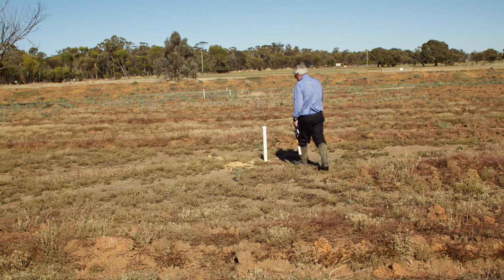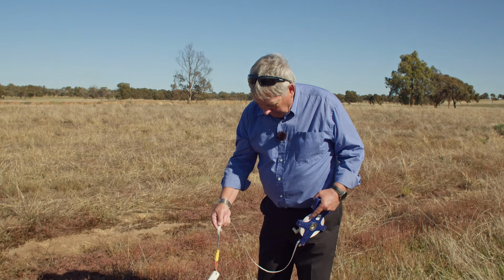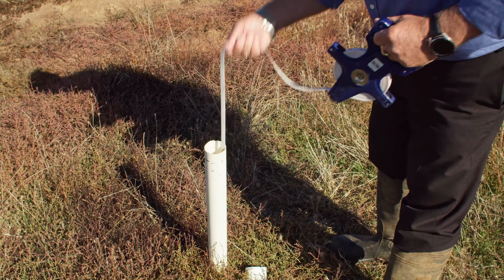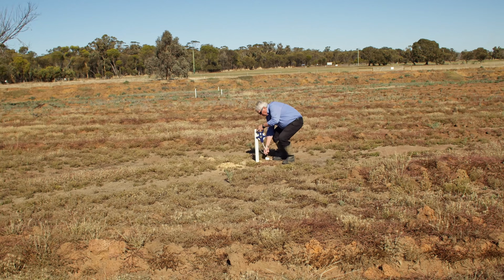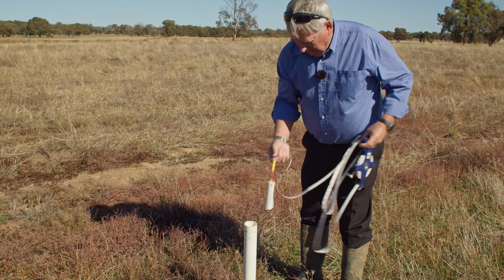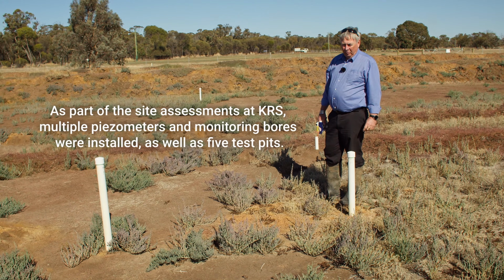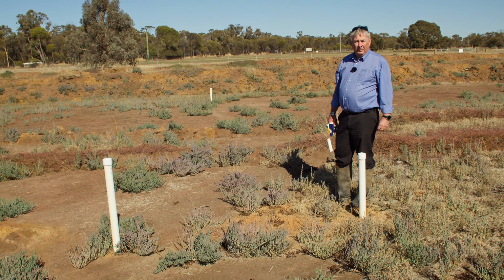At this time, I also suggest to landholders that if possible they put in some sort of monitoring bores or observation wells to see where the actual water table is or measure the rise of the water table at different times of the year. What we've got installed here is a row of piezometers and observation wells. These were installed prior to the drain going in so we get some good baseline measurements. And here we have a shallow piezometer. This goes down to about 3 metres and the deeper one over there normally goes down to around 10 metres. So we can see the effects of the drain after the drain's been installed.